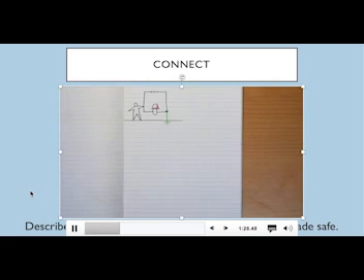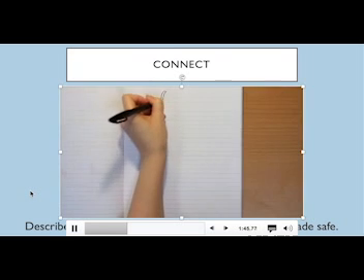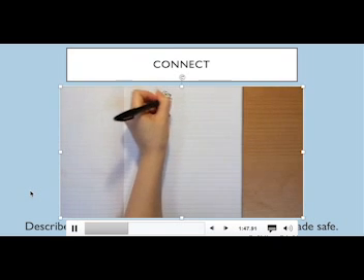230 volts can easily drive a current through your heart that's large enough to kill you if you complete the circuit by touching the live line. Also, if a fault develops, like a short circuit, which provides a low resistance connection between the live and neutral lines or the ground, it can produce enough heat to start a fire. Owing to these dangers, electricity suppliers go to great efforts to make systems safe.